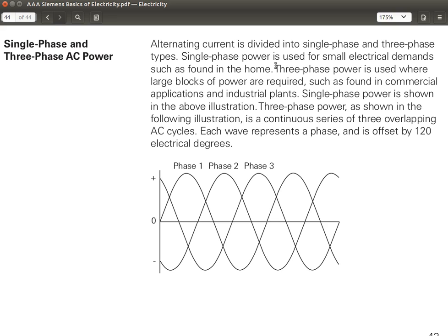The raw or bare wire without any insulation is the neutral wire, and those 2 insulated wires, usually black, wrapped around it, are the 2 live wires. In some cases you might have 1 bare wire and 1 live wire.